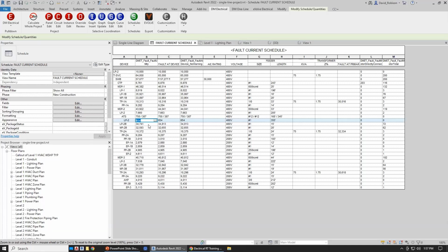If you really needed to have the calculation downstream, you'd essentially have to disconnect this ATS from the utility, run the calculation, see what the values are, write them out somewhere else, and then reconnect everything up. It's not ideal, but that's how our software can handle that calculation for you if you needed the fault on this downstream panel of the ATS in generator mode.